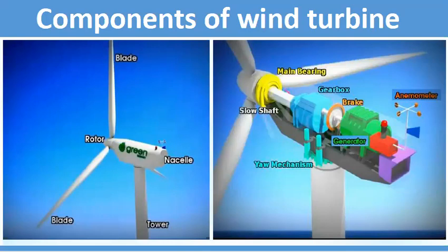Due to the data transmission problem, structural health monitoring of wind turbines is usually performed using several accelerometers and strain gauges attached to the nacelle to monitor the gearbox and equipment. Currently, digital image correlation and stereophotogrammetry are used to measure the dynamics of the wind turbine blades. These methods usually measure displacement and strain to identify the location of defects.